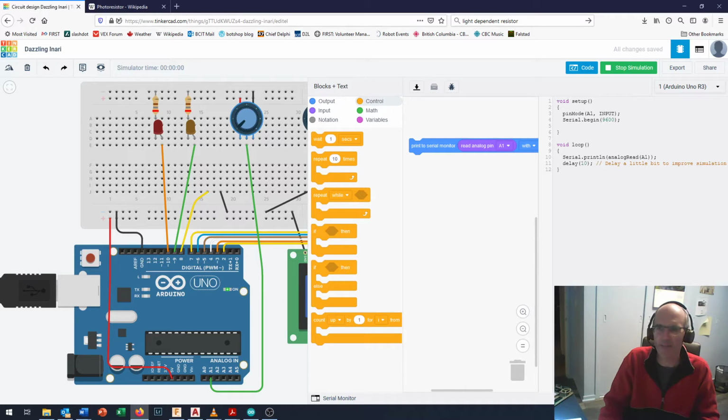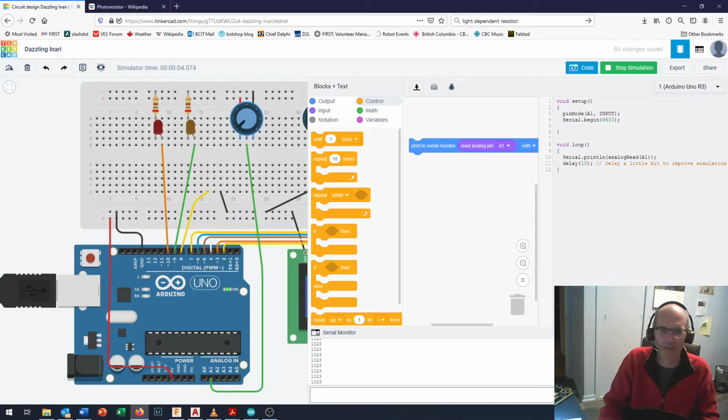Okay, the simulation's running, and now we need to bring up our serial monitor. There's your serial monitor button down at the bottom of the screen. And you can see right here, it's flashing away and telling us 1023, 1023, 1023. That's because our potentiometer is turned all the way up. If you start turning the potentiometer down, there we are, we're at about halfway. Just click and drag that face, 511. That's close enough to halfway for me. Satisfy all those people who told you it was going to be 511 and a half.